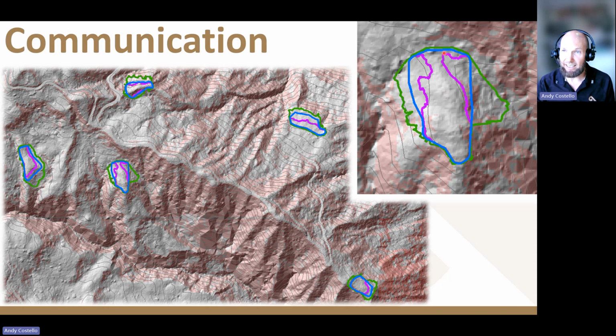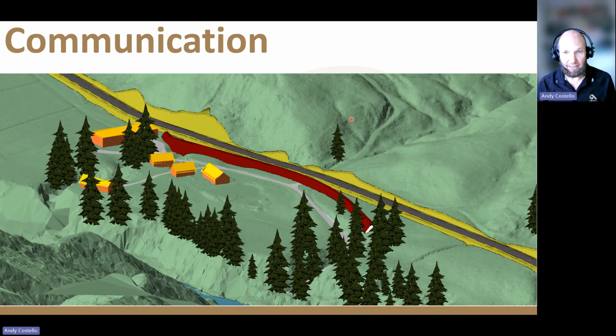And when we mark that on the hill, it's effectively the elevation of the finished skid level. So if they start with the toe bench on the green line and start building up at 30 degrees and stop when they get to that level, we'll end up with a skid that's the right size and shape with all the fill taken care of nicely. So that works well too.